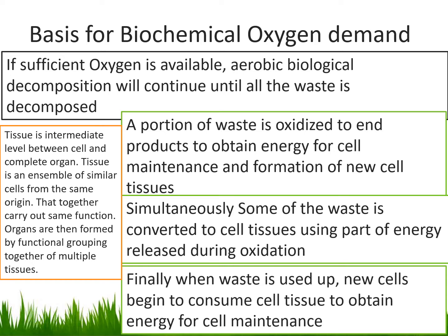So starting with the very simple parts, if we have sufficient oxygen, aerobic biological decomposition will continue until the waste is decomposed. Then a portion of the waste is oxidized to end products to obtain energy for cell maintenance and formation of new cell tissue.